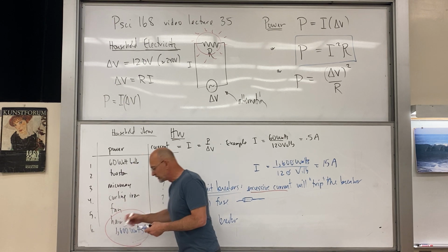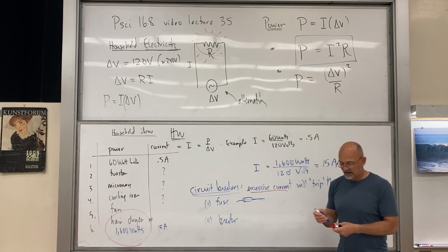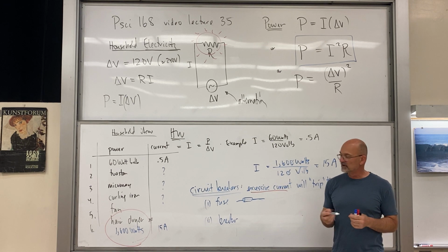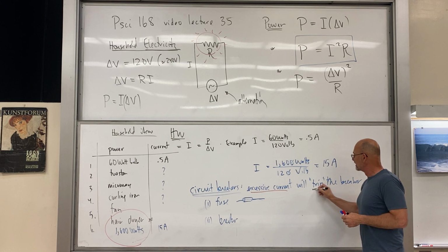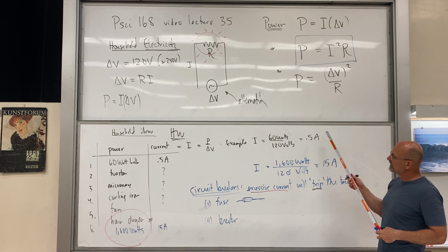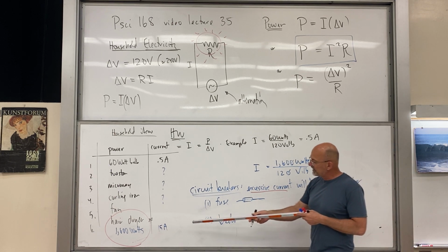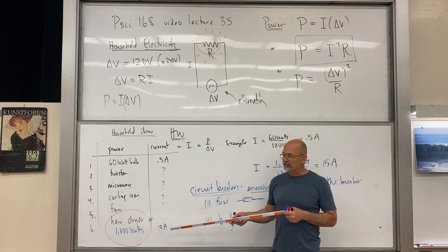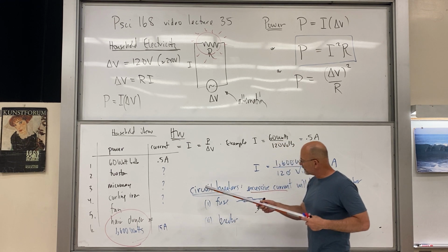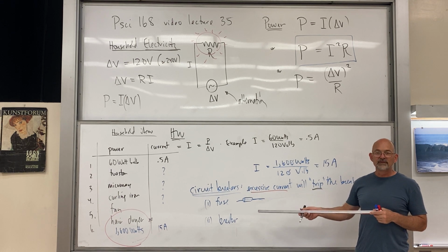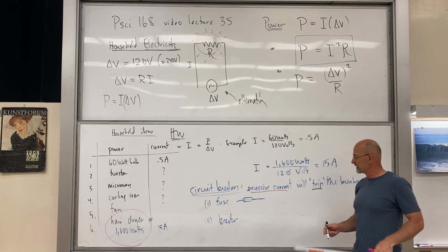I know a lot of students tell me they've experienced that. Maybe with a roommate, they both plugged in the hair dryer at the same time, and the circuit breaker tripped and the circuit shut off. And we can actually see why. If we've got these 15 amps, 2 hair dryers would be 30 amperes, and the circuit breakers in the household wiring will be set for 15 or 20 amperes.